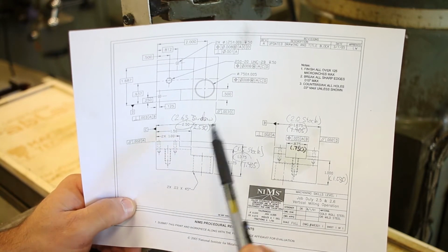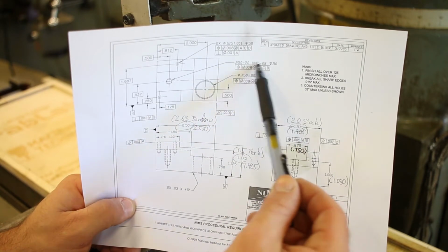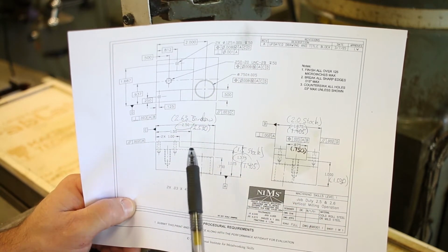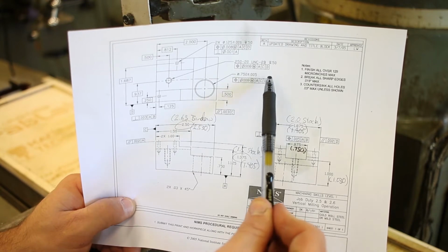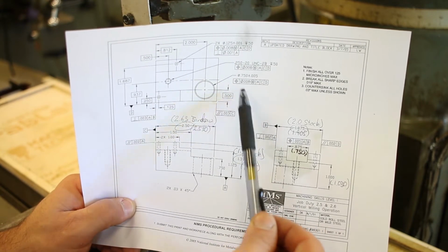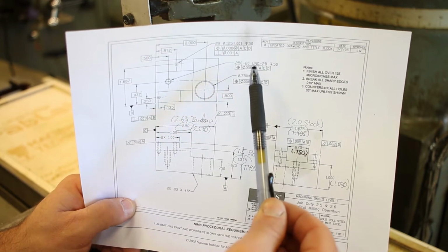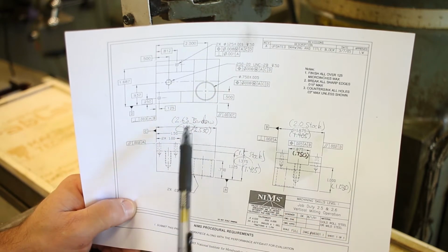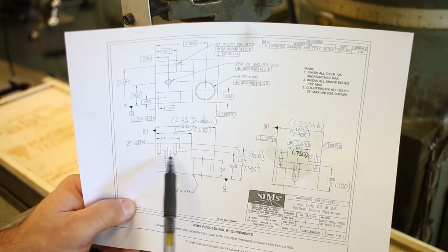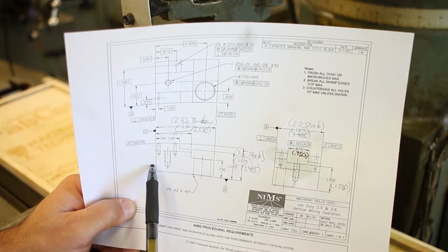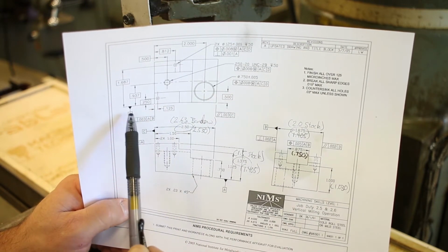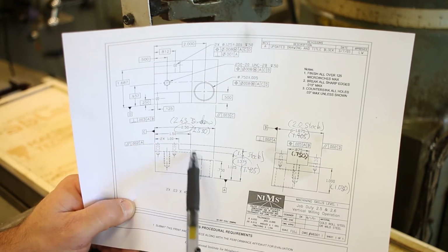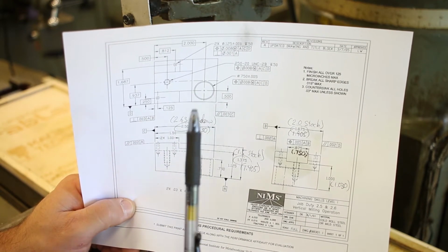Well, for those, we're going to take our cue from the datum reference frameworks for the tolerance of position controls. Okay? A, C, and D. Again, it makes sense to finish these surfaces in their order of priority according to the datum reference framework. So we'll finish datum feature C, which is the left side of the part, second, and then we'll finish datum feature D, which is the front of the part, in the front view here, third.